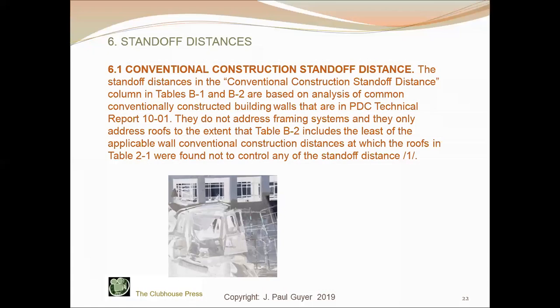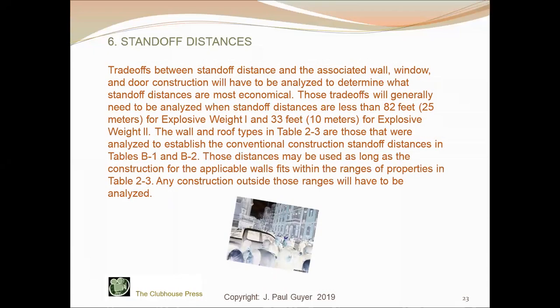So now trade-offs between standoff distance and associated wall, window, and door construction will have to be analyzed to determine what standoff distances are most economical.